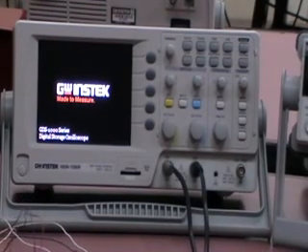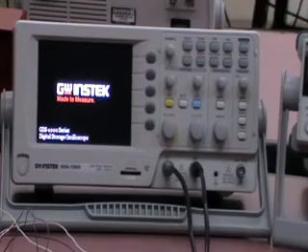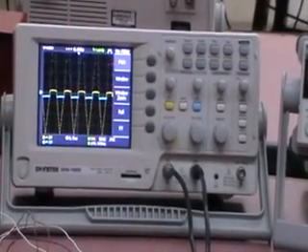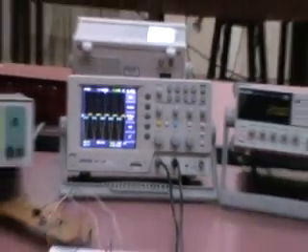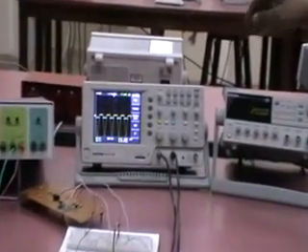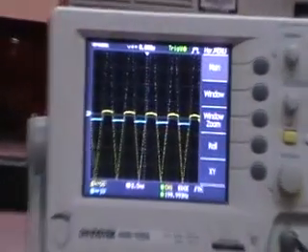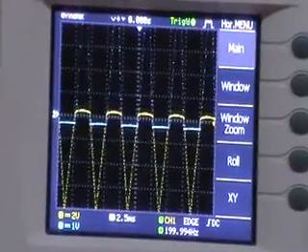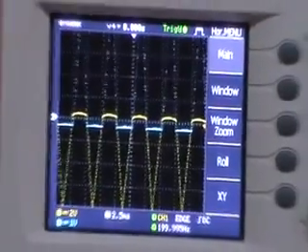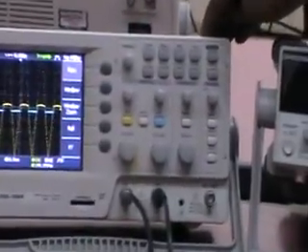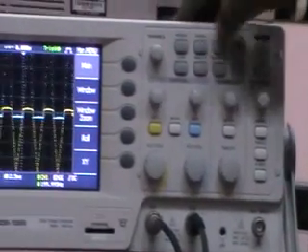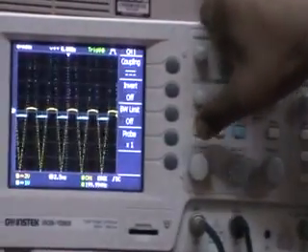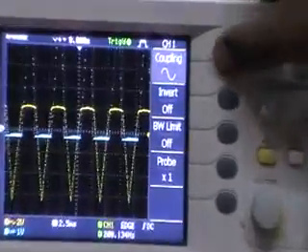So we can observe these are the two output waveforms of both channel 1 and channel 2. So we should observe the IV characteristic along XY mode. To observe waveforms in XY mode, first we should keep the dot across the center. We can verify this by keeping both channel 1 and channel 2 in ground modes.